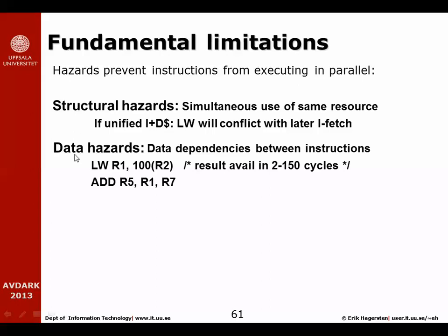Data hazard is probably more common than structural hazard in our pipeline design. Data hazard is depicted here by a simple example. Let's say that you load some value from some memory location into a specific register. And of course, as we know, this is going to be loaded from a cache. If we are lucky, we get a hit in the cache, and this may take 1 or 2 cycles, depending on how fast the design is. But it may also take 150 cycles or 200 cycles or 250 cycles if we have a NUMA kind of memory system. So this could take a long time. And unfortunately, the very next instruction depends on this data being available in R1, because here we'd like to add R1 and R7 together and put the result in R5. So what we have detected here is a data hazard. And this is also bad for pipelines.